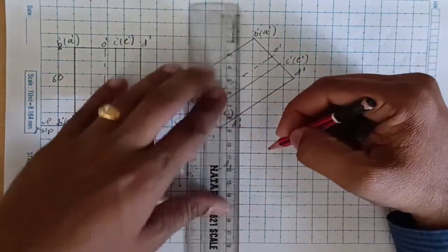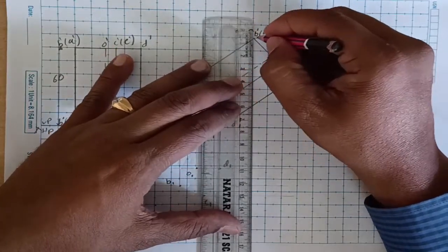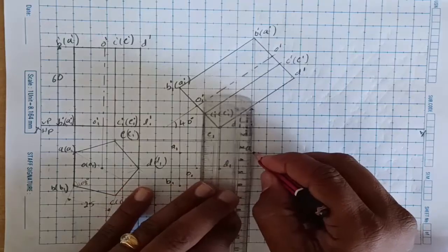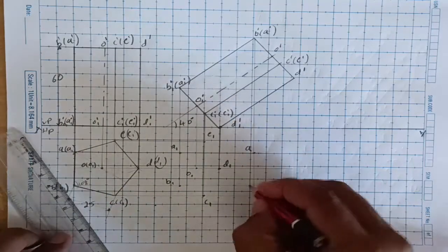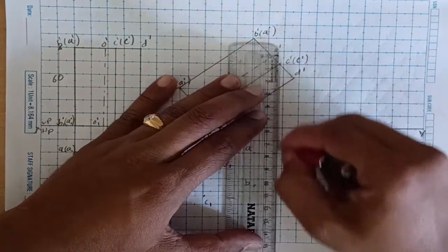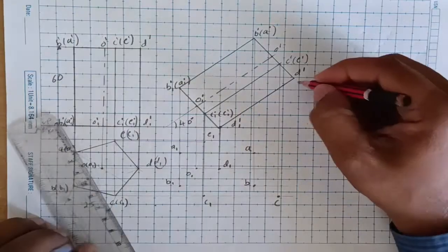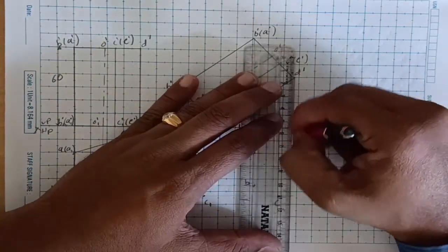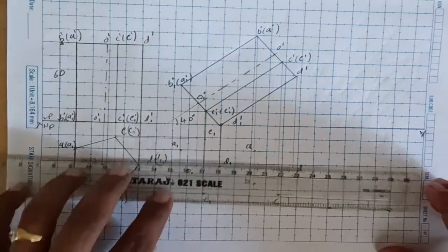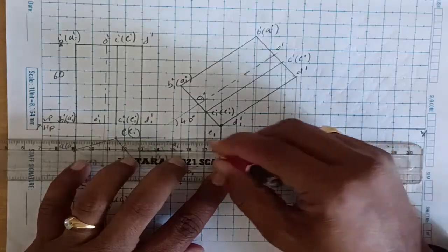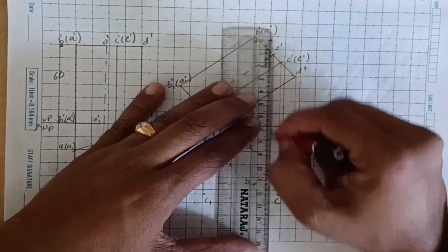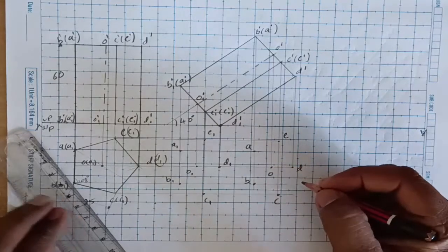and similar way top A, B, C, D, that is A dash, B dash, we need to join it here. A line is there, and here the A dash, you can draw the vertical projection up to that and get the A. So this point is A, and same if you extend, we will get the B. On this point I will get B. And then C. C dash is here, and then up to the bottom here I will get the C, and then D on this point I will get D over here, and then E, we can draw the horizontal line from here, and this point is E, and the last center O dash, and this is O, and this point is O. And now we got all the points.